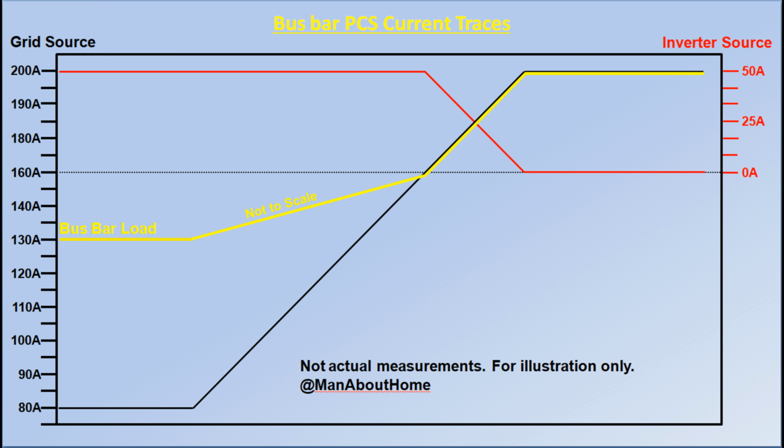When the busbar comes within 80% of your PCS set point, the inverter will gradually reduce the amount of export power to protect your busbar. Ultimately, if there's 200 amps or whatever the adjustable set point dictates coming in on the main breaker, the inverter will be exporting 0 amps. I'm thinking I want my set point to be 160 amps. That's a number that will be very safe and maintain all my energy needs at the same time, because the inverter will start down modulating at 80% of that, or 128 amps, which my system will never be consuming anyway.